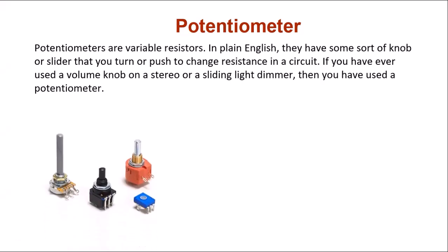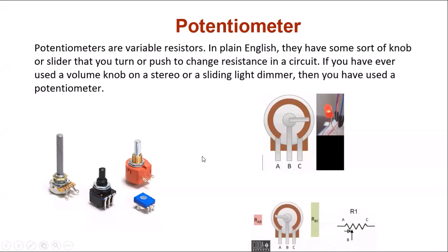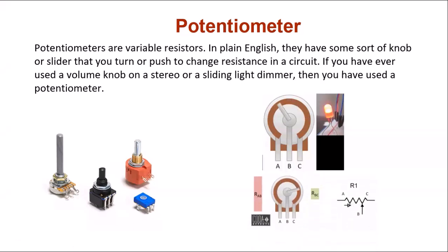These type of things are called a potentiometer. How does it work? You can see from here, as you are rotating, the light bulb LED is dimming or working in full bright condition. And this is the only function. And how exactly does it work? Like this. You can see at the bottom, the variable resistance is varying. Lesser resistance, more light. Higher resistance, less light.